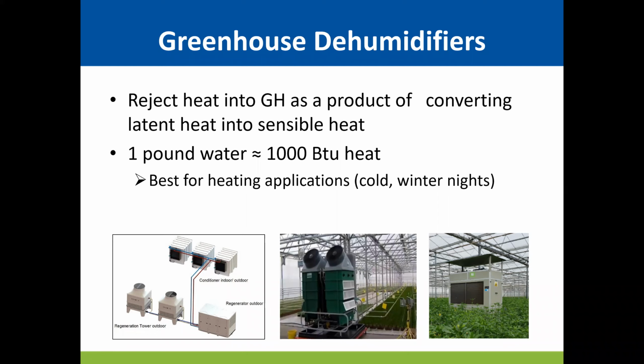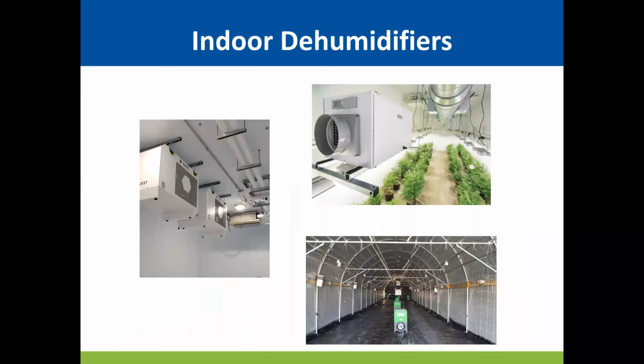There are some new technologies that are coming online, like this one that's also using liquid desiccant that rejects that heat to the outside using cooling towers and chillers. You can also use chilled water to do this or refrigerant to do this, but the key is you have to reject the heat outside, so you're only doing dehumidification, say, in the summer when it's hot and humid inside. Indoor dehumidifiers, I'm sure most of you are familiar with a lot of these technologies, right?